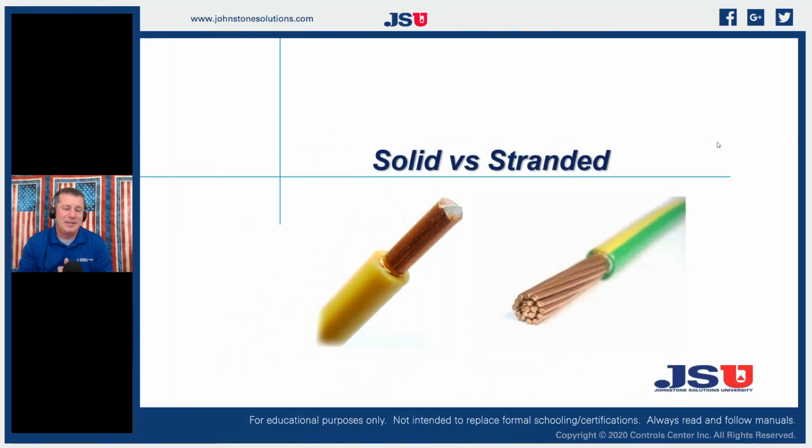So one of the things I wanted to go over is the difference between solid and stranded wire. Because when we start talking about installations, particularly for mini splits and multi-split, so multi-indoor head units, and VRV, and now things like the Daikin Life systems and our Daikin Fit systems, these are all communicating systems using low voltage, 5 volts DC, to communicate from the indoor to the outdoor units. We're doing something that is a lot different than what we have done in the past.